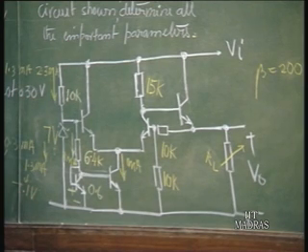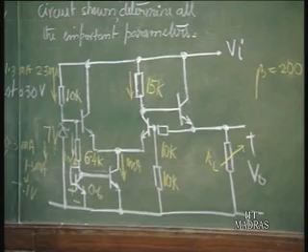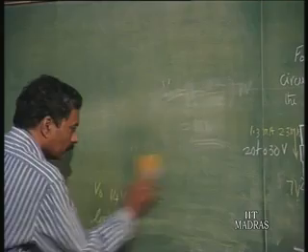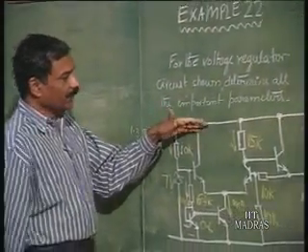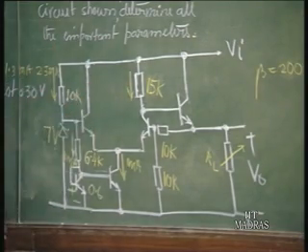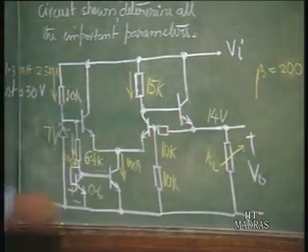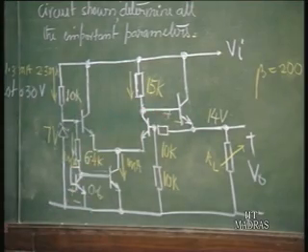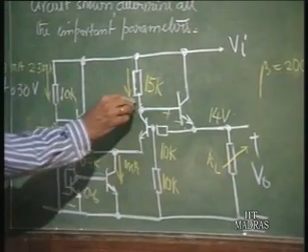we will also know what is the variation of current that is occurring here. That is, this we had mentioned about earlier. Because Vi is changing from 20 to 30 volts, the current here is changing. What is the voltage here? This is 14 volts, okay, and this is 14.6, let us say, V gamma more.